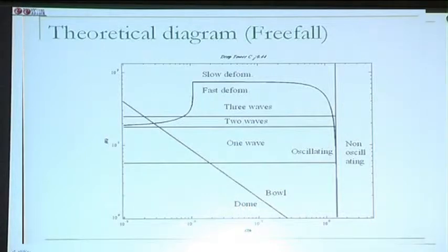But what is very strange is that if you look at this limit here, it's around 80 for the Weber number. Most of the time, it's around the same zone, the same kind of value that is used to distinguish between the bag breakup and the shear breakup. So it means that shear breakup must appear in this slow deformation area.